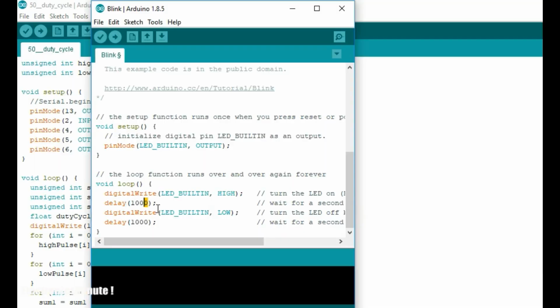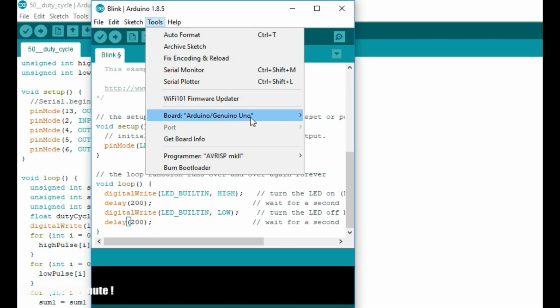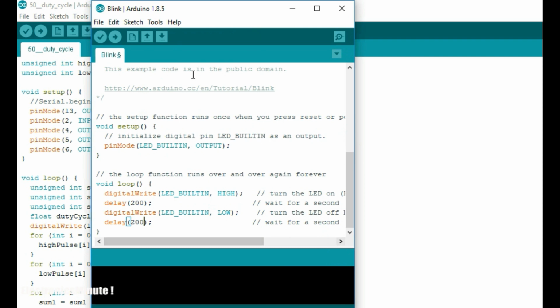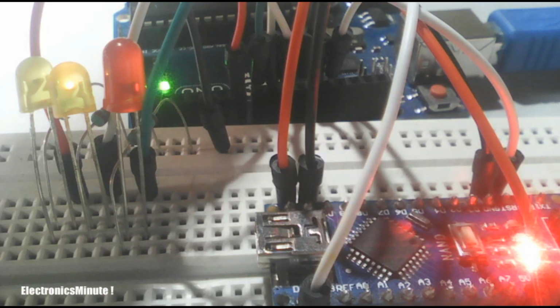Then I continued by creating a new blink sketch as an example, selected the board type as Arduino Nano, the microcontroller as 328P, and the programmer as Arduino as ISP in the Tools tab, and uploaded the sketch from the Sketch tab by choosing upload using programmer. The programming LED on pin 7 will blink rapidly and there will be no errors, meaning the red LED on pin 8 does not light.